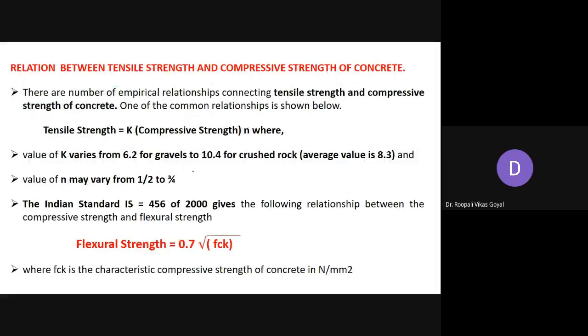Now we know how to find out compressive strength and how to find out tensile strength. But it is generally observed in the field that we invariably do compressive strength testing, and less stress is given to finding out the tensile strength. There are certain studies that have developed relationships between tensile strength and compressive strength of concrete. So if you want to find out tensile strength based on the compressive strength of the concrete, that can also be done.